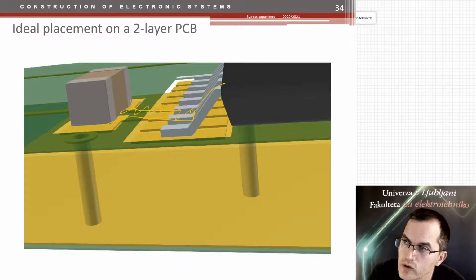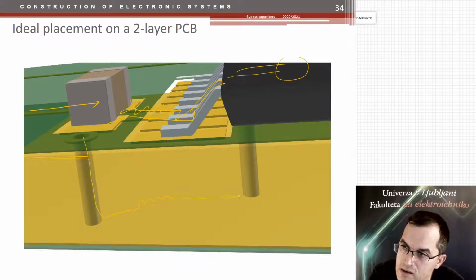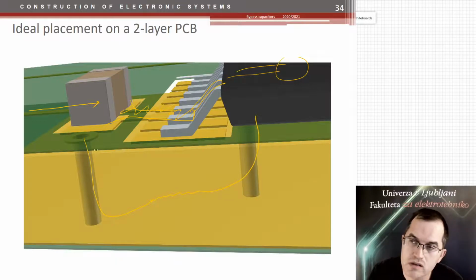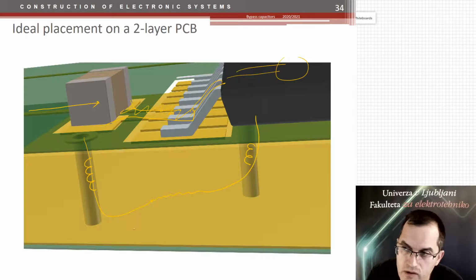Of course, you have to account also for the leads all the way down to the chip. And the power comes from here. The ground also has this row, so this is another connection on the ground, which is better in terms of the impedance. Here is the impedance, of course, of the wires, the inductance of the wires, but inductance on the ground plane is very, very low. So this is then connected in parallel with the ground connection.